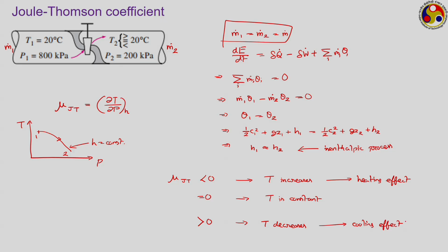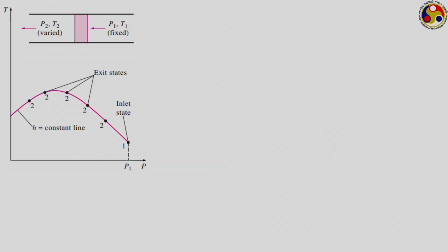So, in choosing a refrigerant, we have to ensure that under the given circumstances the value of the Joule-Thomson coefficient is a positive one. Now, this discussion is for a particular enthalpy. Similarly, for every given value of the inlet enthalpy, the nature of the Joule-Thomson coefficient will show a certain kind of trend, and that is what is shown here during this simple experiment.